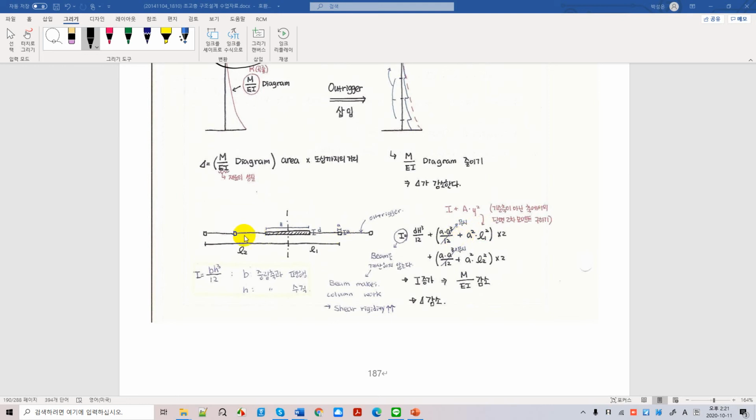And we have 1 and 2 here, right? And there is another one here, so you can do the same thing here, with L1, and this is L2 here, right? So you can do this for all columns that belong to the outrigger system, and you will find that your moment of inertia increases, right?